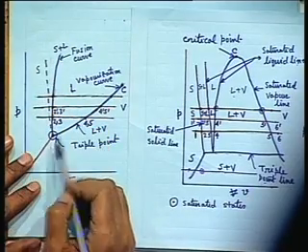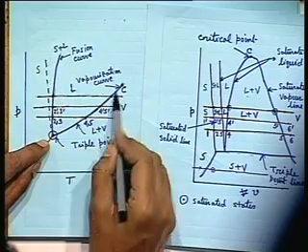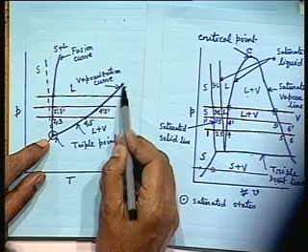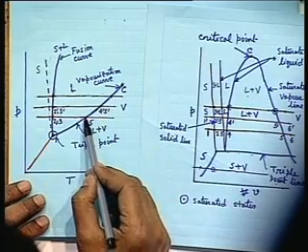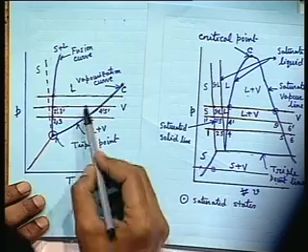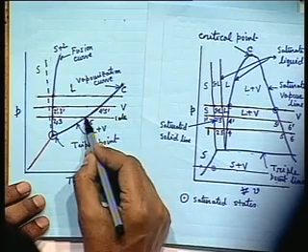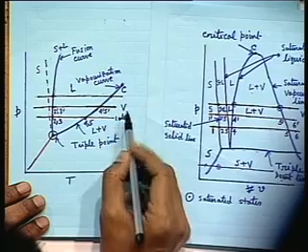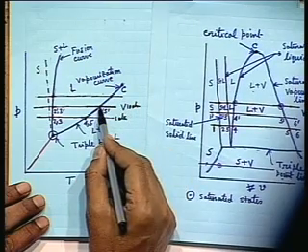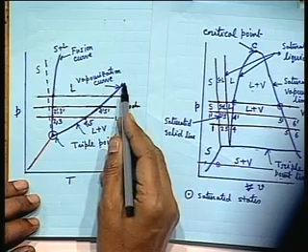This is the gift of nature, so that these two curves meet at a point, whereas this curve is very flat, which means the pressure has a dominant influence on the vaporization temperature. That means this is 1 atmospheric pressure, and this temperature is 100 degrees Celsius; if we change the pressure to 10 atmospheres, there will be a substantial change in the temperature for vaporization. So this curve is relatively flat.